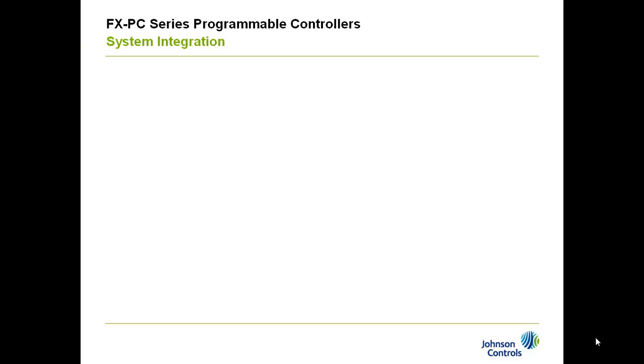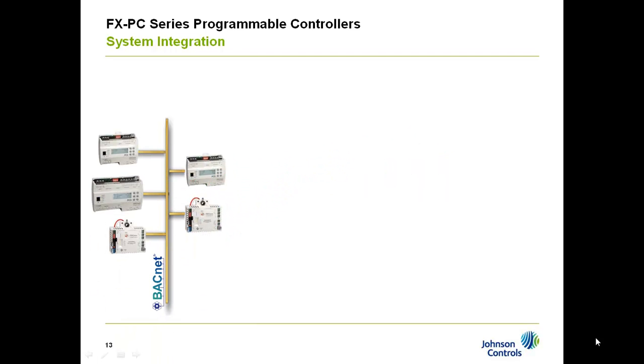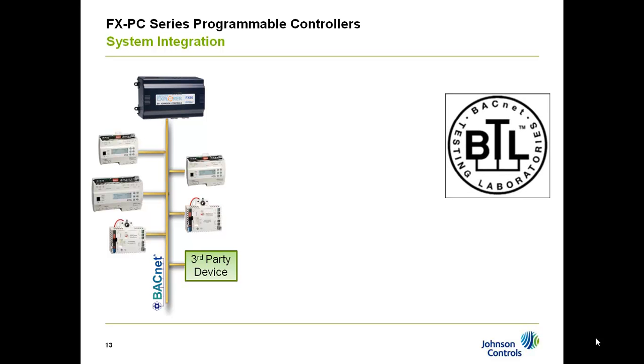All FX-PC controllers communicate via BACnet MSTP. FX-PC controllers can exchange information over BACnet with each other peer-to-peer, with FX Supervisory controllers, and also with third-party BACnet devices. FX-PC controllers are BTL listed as BACnet application-specific controllers, which independently validates their BACnet interoperability.